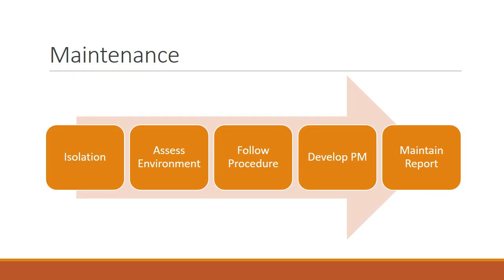Now next, we should develop a good maintenance plan. You should make a timetable on how frequently you will do preventive maintenance on your switchgear. And this considers factors such as the criticality of the equipment, its condition, and the kind of switchgear it is. These are only suggestions, but they are a good place to start when it comes to creating an efficient preventive maintenance plan. Reliability and uptime will rise if a proper preventive maintenance plan is used, and the total cost of ownership will significantly reduce if you maintain your equipment on a schedule that minimizes the impacts of wear and tear, as well as the environmental conditions that it is in.